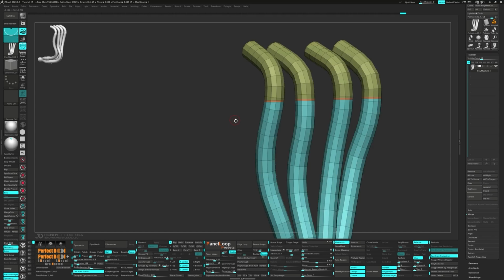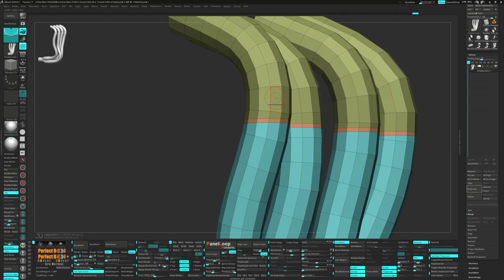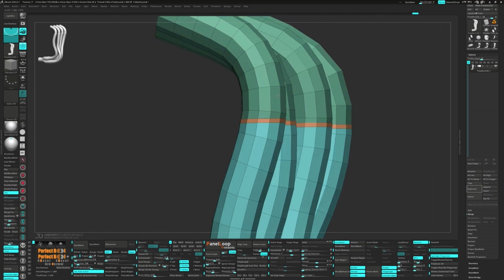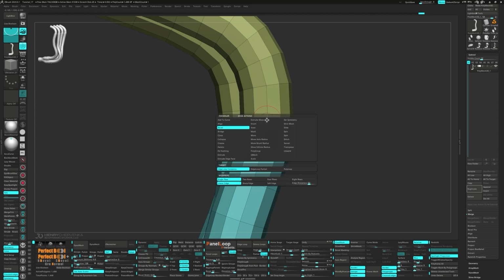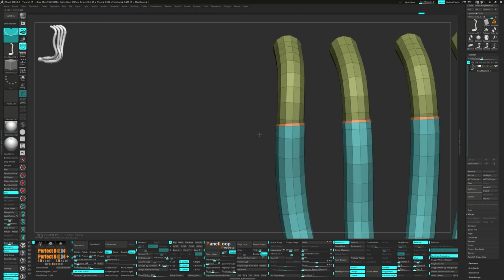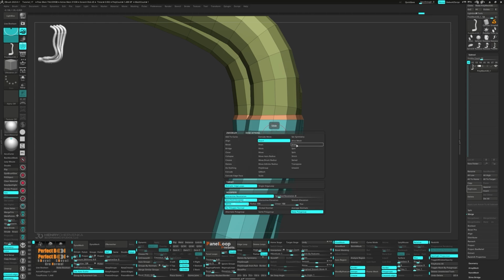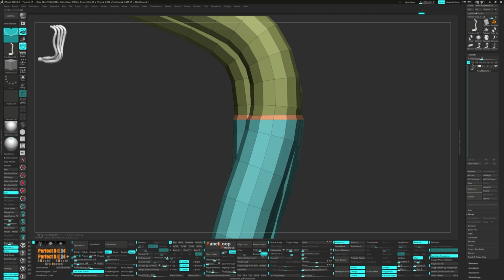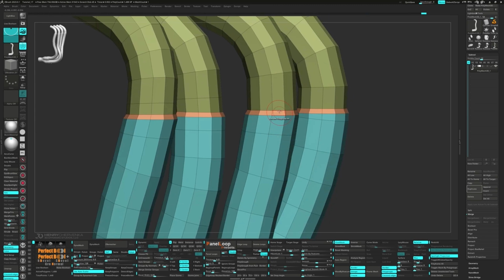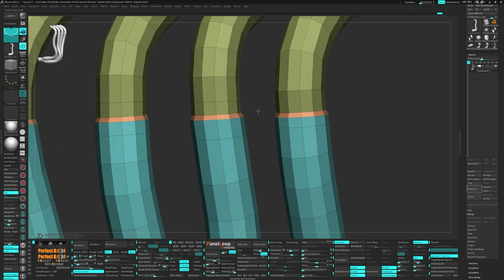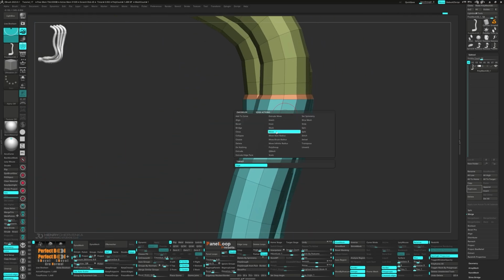Next we can polygroup those bevels. For the polygon action, select Extrude, and for the target, select Polygroup All. Press the Shift key to switch it to a move operation. From the ZBrush, select Slide Edge Loop Complete. Then we can make some adjustments with Move Infinite Radius.